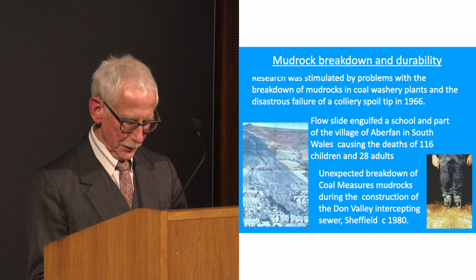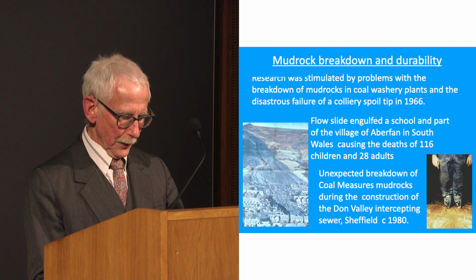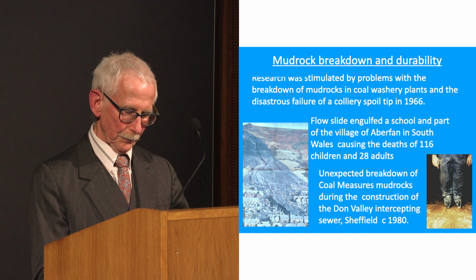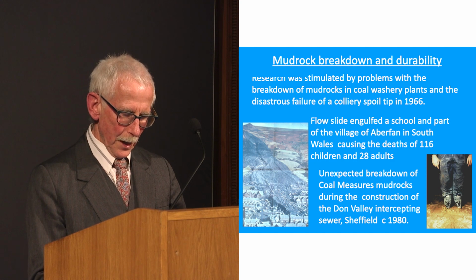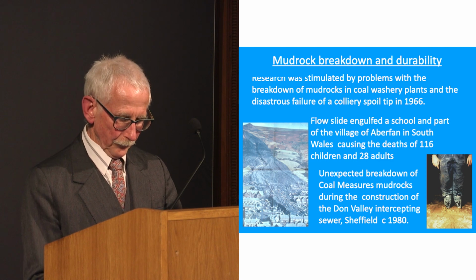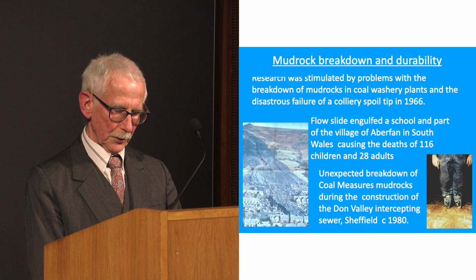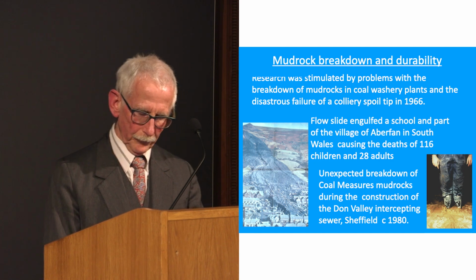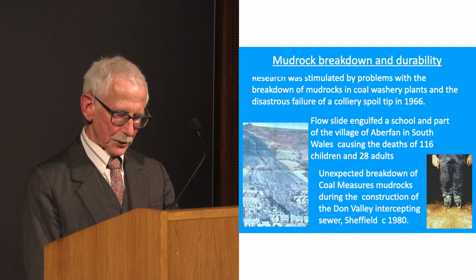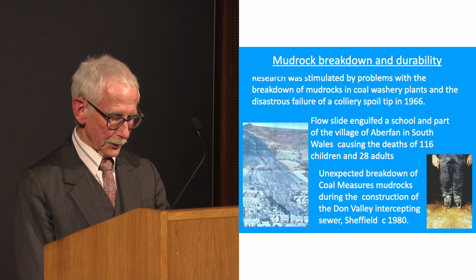In the 1980s, at Sheffield, I was asked to assist with the ground investigations for sewer tunnels in that city. And one of the problems they had encountered on earlier contracts was the formation of a clay slurry, which was difficult to remove from the excavations. Whereas the rock fragments could be removed on the conveyor system, the slurry had to be removed by hand in skips, which greatly delayed the tunnelling process.